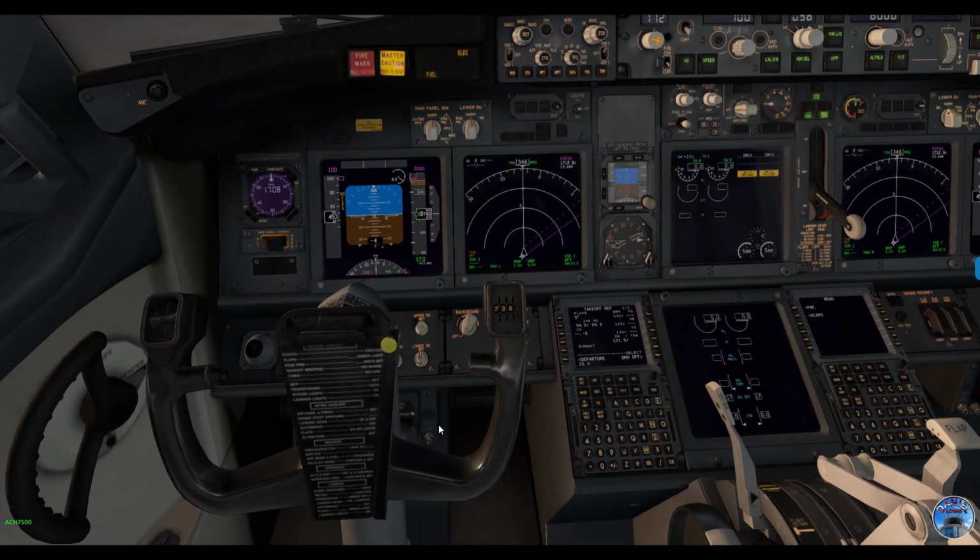And the flight management computer has calculated the takeoff trim is 4.75. And last we set the takeoff speeds calculated.